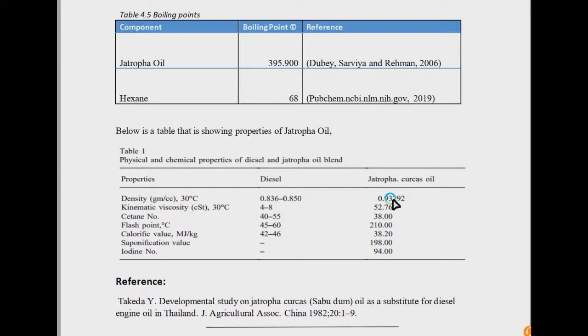We have certain extractor operating conditions also, like here I am again saying T in is 25 degrees centigrade and T is 50 degrees centigrade, assuming that no temperature gradients or dead zone exists inside the extractor. So using this equation we can find out that the heat released during the whole extraction process is equal to 874386.4 kilojoule per hour.